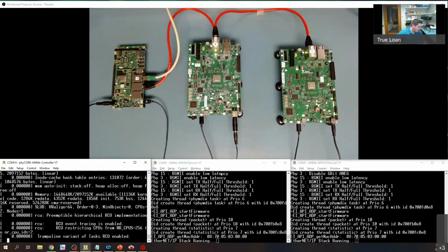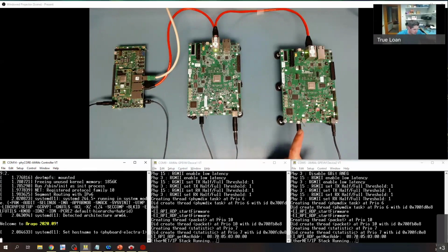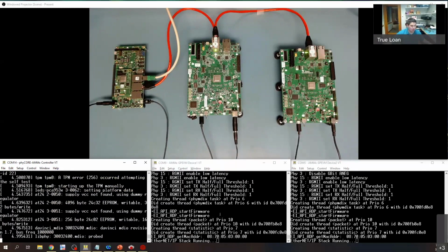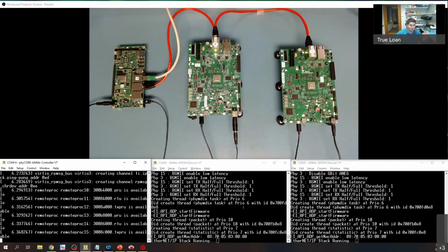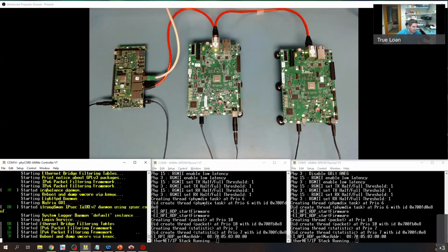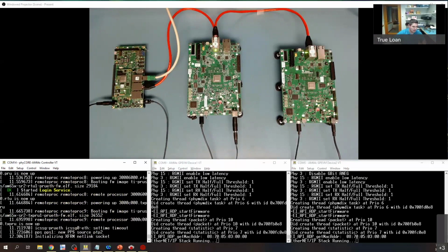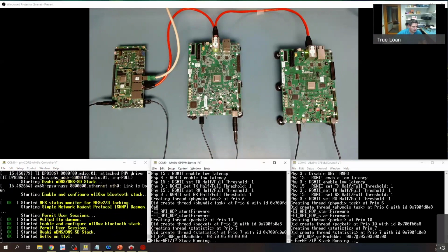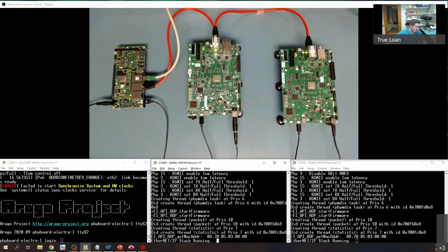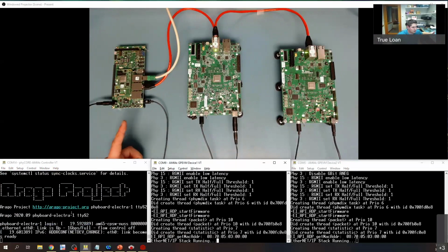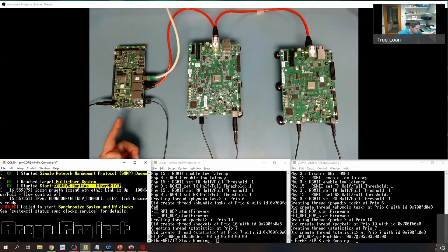All right, so what I've done there is I just switched to OSPI boot mode, and we can see that off screen, before the webinar today, I installed and built those default Ethernet IP examples, just like we did with Profinet. So I haven't really modified anything here on the secondary boards. And you might have seen me switch the SD card for the main board here. That's just because I've provisioned this SD card with another CodeSys runtime specifically set up with an Ethernet IP network that I built just the same way with CodeSys. You just saw me do that live with Profinet. I've just done this beforehand.